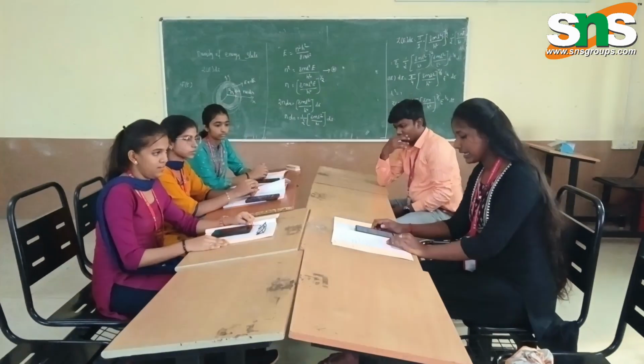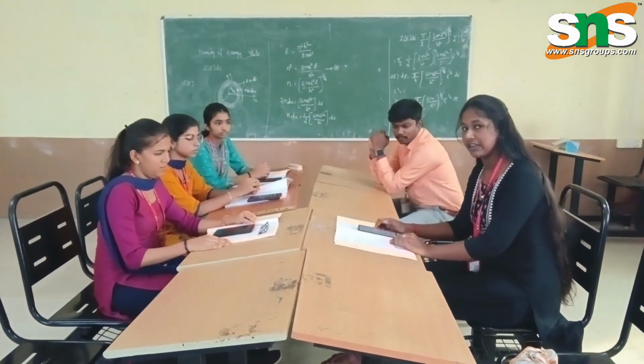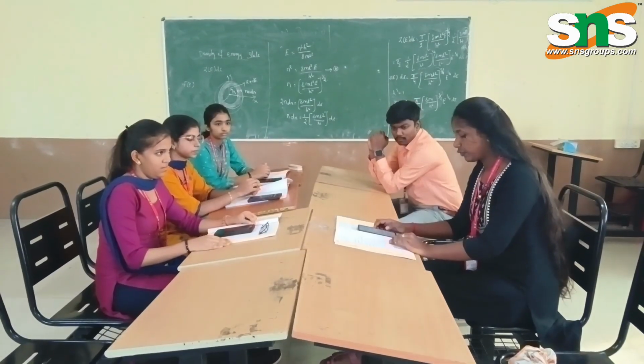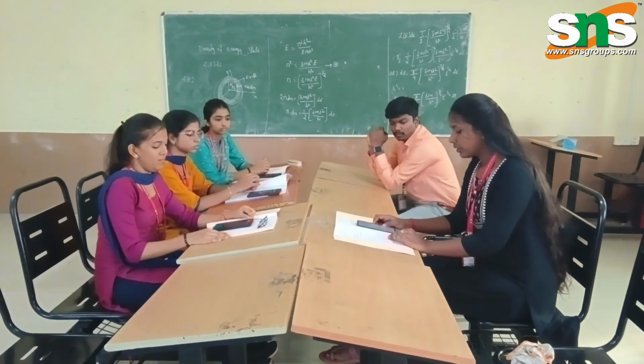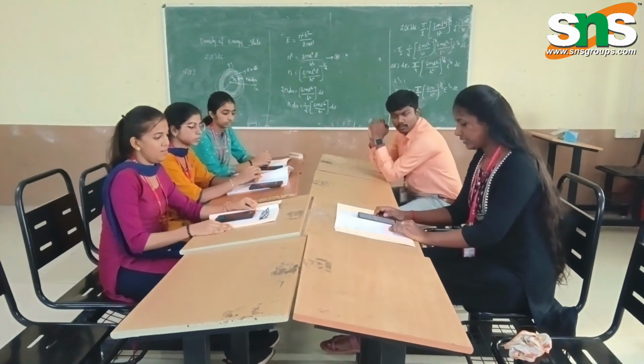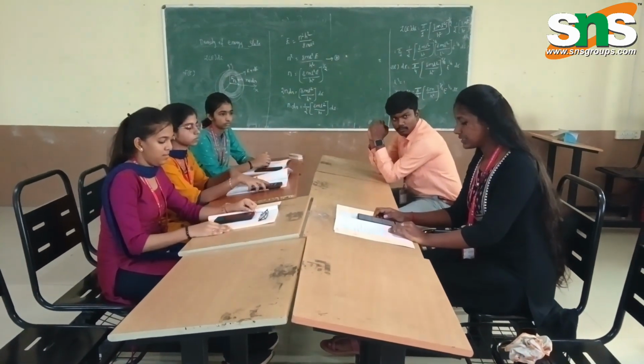And the third one is line parallel to both HP and VP: top view is true length and front view is true length. And the fourth one is line inclined to HP and parallel to VP. Front view is true length, showing the angle. Top view is shorter length.